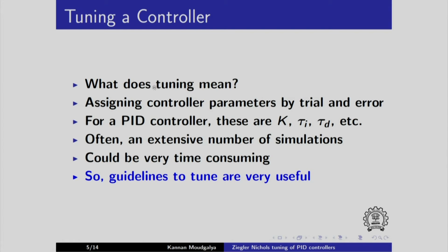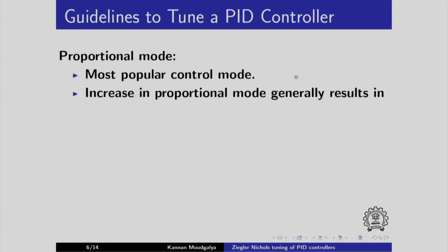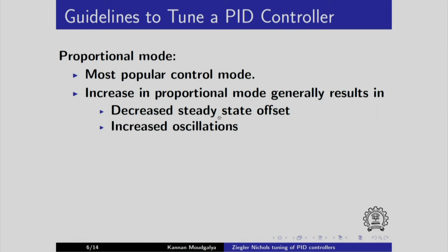Why is the word tuning? In old days we had radio knobs. Using the knob we used to tune them, so we call it tuning a controller. We will next take up the guidelines. Here are guidelines to tune a PID controller. Let us consider the proportional mode. It is the most popular control mode. Increase in proportional mode generally results in decreased steady state offset, increased oscillations.